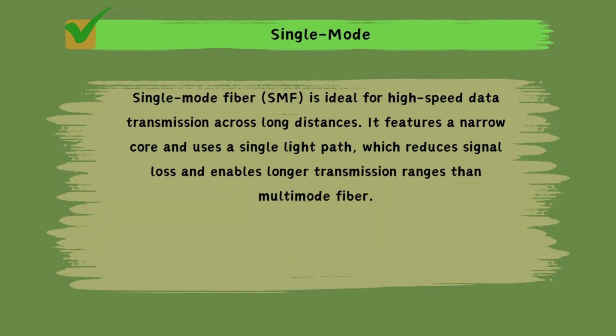Single mode fiber is ideal for high-speed data transmission across long distances. It features a narrow core and uses a single light path, which reduces signal loss and enables longer transmission ranges than multimode fiber.